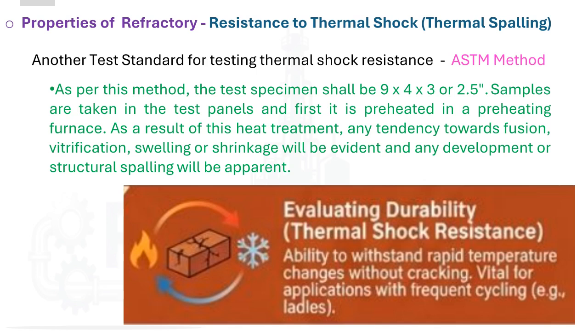Once preheating is complete, the real thermal shock test begins. The brick panel is quickly heated to a specified temperature within just a few minutes. And then, without warning, it faces rapid cooling, a blast of compressed air, or sometimes a spray of water, depending on the test variant. This sudden change creates a far more dramatic thermal shock than the slower cycles used in the British Standard method. After the test, reporting is detailed.